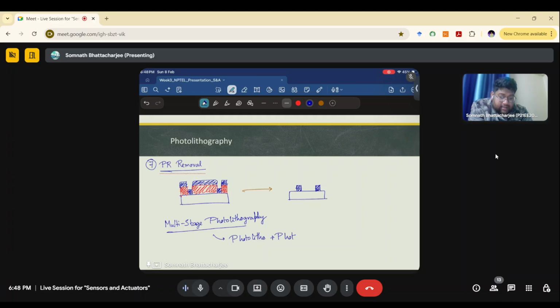In these cases, your optimization steps become very useful, because if there is an error in the first stage, there will be more error in the second stage, and based on that, the error will increase exponentially. So you need to perform perfect lithography in the first stage. If the patterning is very clear in the first stage, and you have a mask that contains, let's say, two or three different structures or designs, you need a multi-stage structure to be made. You need multi-stage photolithography.